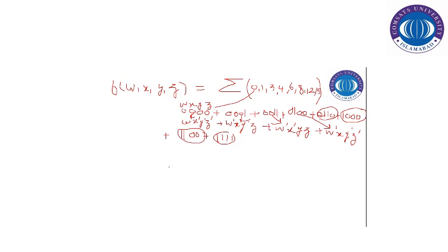As far as the simplification is concerned, if we have to implement the function by using the minimum number of resources, we have to use those techniques that are used to simplify the expression. Now, either we can use Boolean algebra or we can use some mapping techniques, for example, the K-map technique. So let us discuss the mapping technique here since we have studied that. So we have to construct a map of 4 variables here.